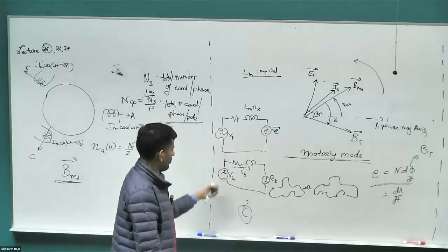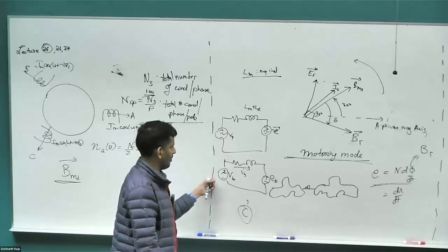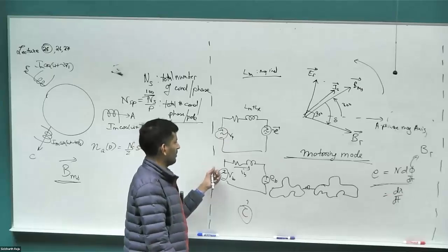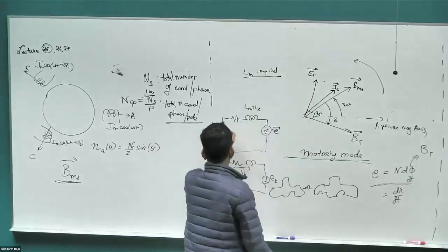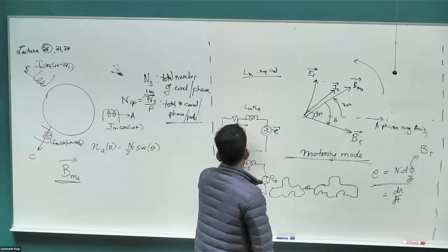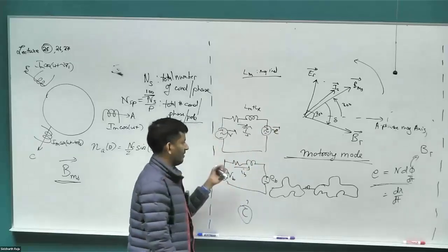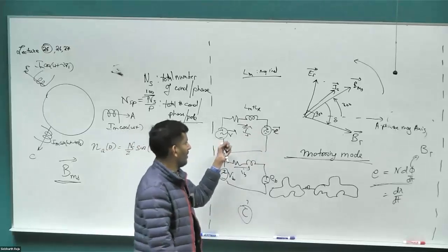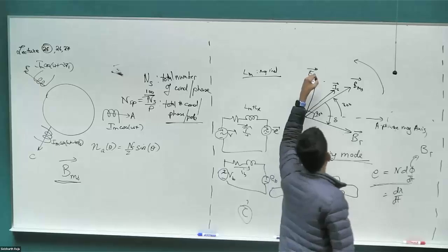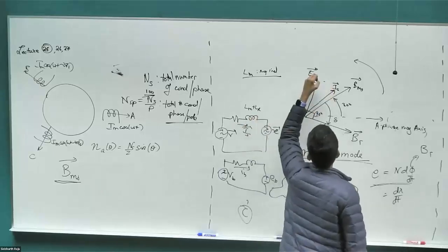And then you plug this voltage into the space vector transformation. It will be the same as if you just considered the space vector itself as a circuit variable. Right? Instead of doing this, if I consider this current itself as a circuit variable, and the EMF space vector itself as a circuit variable, it's a single circuit that I can quickly solve. Right? So we take this, add IS space vector times RS.